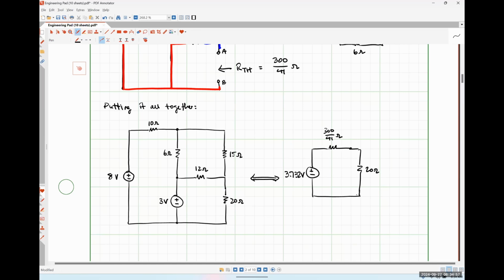So let's talk about where a Thevenin equivalent circuit would be used in practice, okay? Because as far as an analysis tool, it can have its uses. Like I said, if you have something particularly complicated that you can make look like a two-terminal network by disconnecting it, you can just find the Thevenin equivalent and plug that back in. Okay. If we wanted to know, let's say we were designing a piece of electronic equipment, and we needed to know whether or not our load was going to be supplied with so much power that it could likely burn out or something. Instead of analyzing our circuitry, we would just find the Thevenin equivalent with respect to our load.